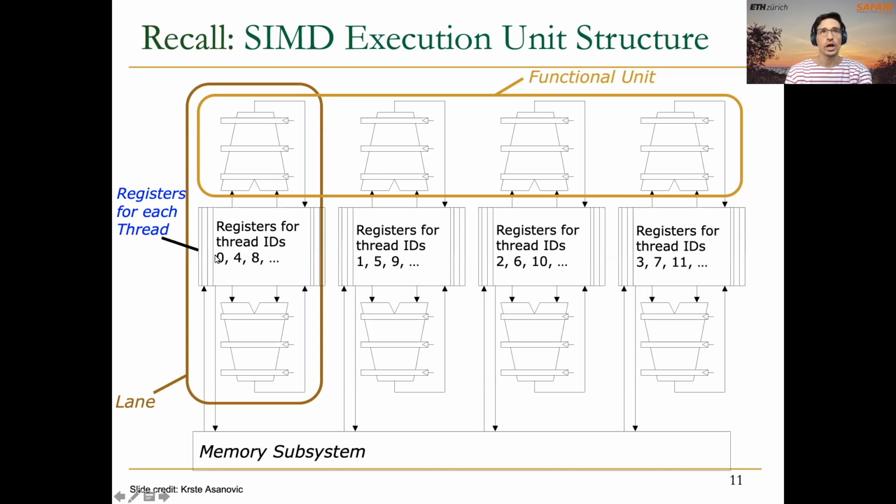And also we have the partitioned register file, where we have the whole amount of registers that, at the beginning of the execution, are partitioned and assigned to the different threads that are going to run inside the GPU core, or inside the SIMD processor if we are talking about SIMD processors. And remember as well that this combination of registers assigned to individual threads plus the corresponding execution units inside the different functional units where instructions from different threads are executed is called a lane.